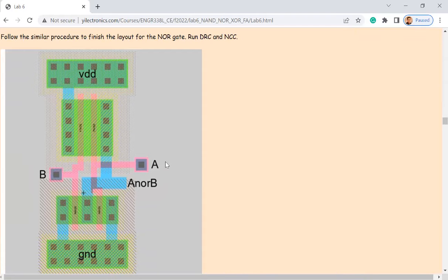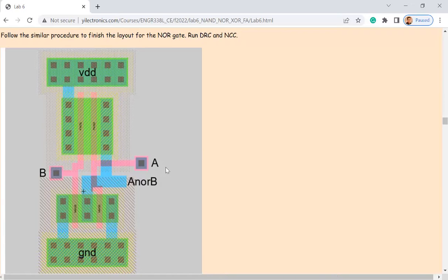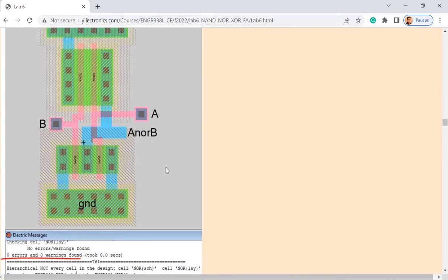Okay, so this is what you are going to have. So no space, because these two are too close to each other. So the poly layers are too close to each other. You have to draw it that way and introduce another input over here. So you can directly draw a metal 2 via here and then introduce the left-hand side. Same here. Okay, I have both inputs on the left-hand side and output on the right-hand side.